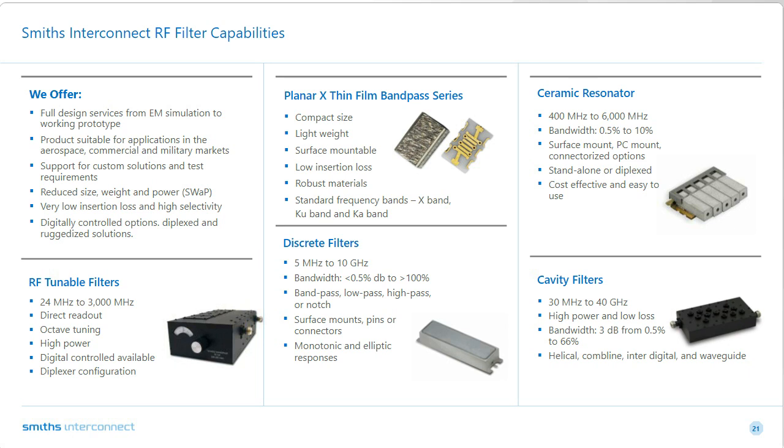How accurately do you control the dielectric constant in your high K material? So I can answer this one. We usually have a tolerance of about plus or minus 1 for something that is around a 38 dielectric, which we most commonly use. And we can always simulate and run Monte Carlo analysis to make sure that each variation of that dielectric will pass over the temperature extremes.